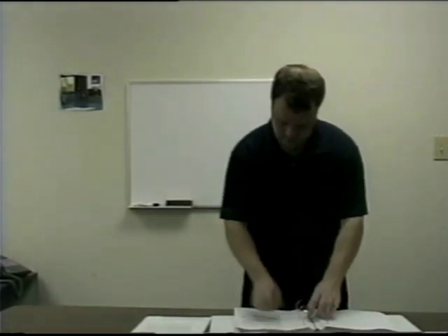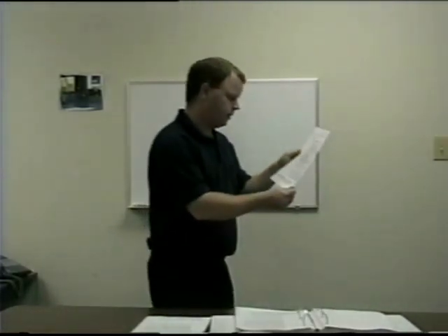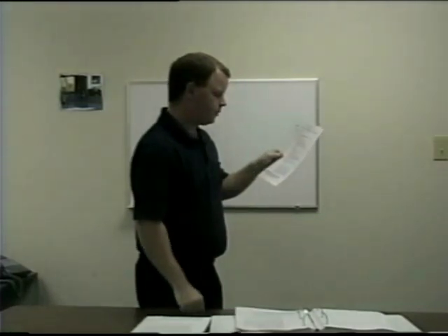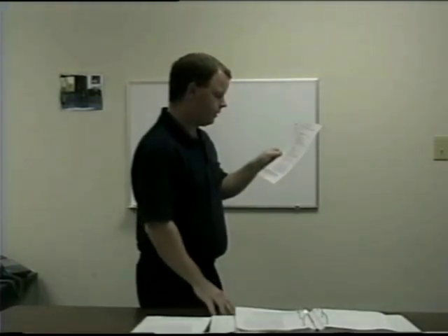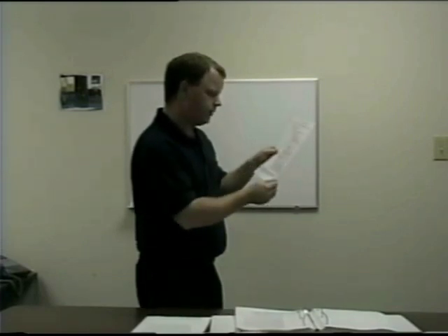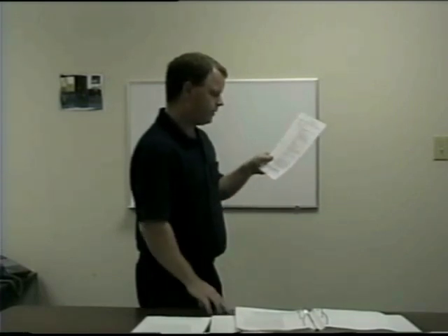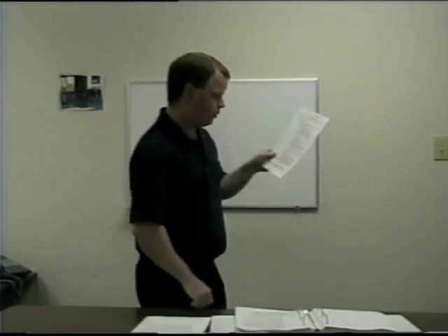Look here. We've got membrane roofing. Verify materials of types required are provided. Verify softening points of bitumen is as required. Verify materials are identifiable and comply with the ASTM and FS standards. There we have industry standards. Okay? It's all spelled out here what the standards are.